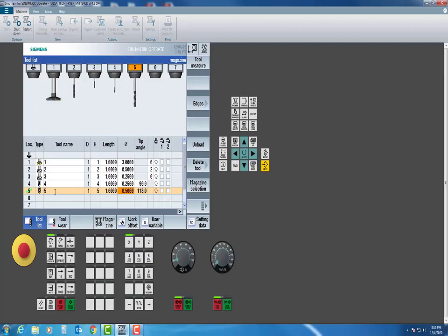Now it is important that you get these diameters correct or else your simulation will not work properly. If I put that as a 125 thousandths diameter, that hole would be very tiny. Okay? So this will actually help with your simulations to see if you are running it correctly and if things are coming out in tolerance. So with that said, all of my tools are built.